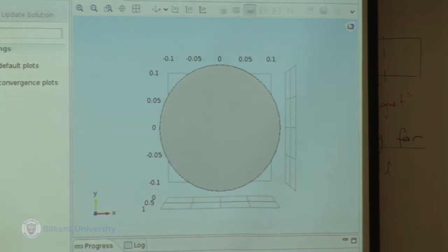It will take a little bit. I can do several things. Instead of pulling, I can push. Instead of having a right-hand chirality, I can have a left-hand chirality. The Poisson ratio here is 0.3. I can make it minus 0.3. So in other words, when I pull, the material will not try to contract. It will try to expand. Three major variations: chirality, direction of displacement, and the sign of the Poisson ratio. Okay?